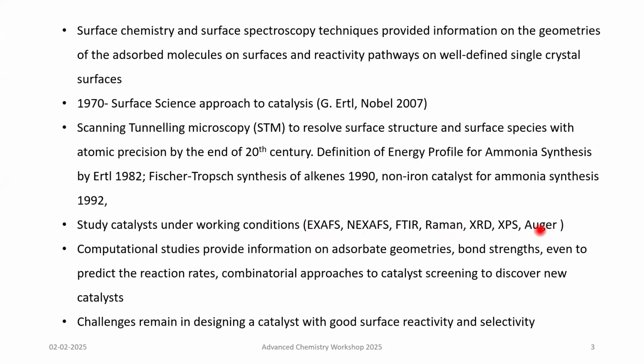Okay. So there are three steps here. One is synthesis of a catalyst with a particular activity and selectivity, which is a challenge. That requires a lot of chemistry background, chemical knowledge, and knowing what exactly the product is that you are looking for. Once you prepare that, you have to see whether what you have prepared is the correct one that you wanted to prepare. For that you need some spectroscopy and microscopy techniques to check whether it is formed properly or not. Once you are convinced, then you use it for doing the reaction. Okay. So these are the steps involved in this.